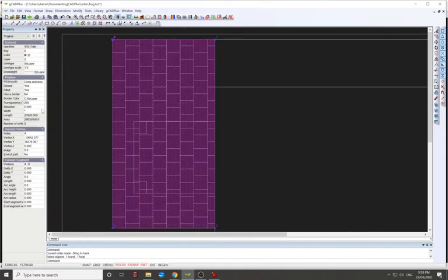We select that again. Now there is some problem with this because apparently if you go to print this out, it works okay, but what I'm going to do is put some transparency on it. So if you use the polyline and you enter filled and you've put a solid color in, you can add transparency to it and you can print it out on the printer. But you can't add transparency to a hatch that's a solid hatch because you've got no option to add transparency to it. And at the moment, when you go print to PDF, you aren't able to add the transparency to the PDF, I don't believe.